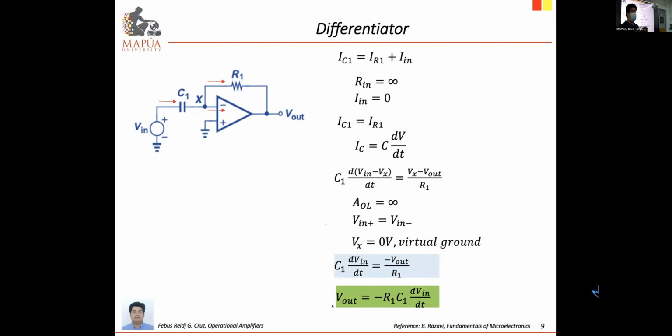By the way, the product of resistance and capacitance is also referred to as the time constant. It describes the delay on the circuit. All right, so product of resistance and capacitance would give you the delay, the change in voltage for around 63%. All right, then it will take 5 times R1 and C1 for the capacitor to be fully charged or fully discharged.